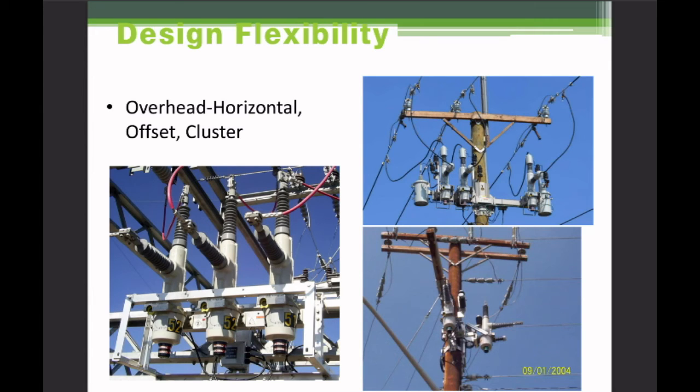If we take a look at this one, for example, you'll see there's 3 individual switches, and they go back to a central control box that'll feed down the pole. And so this is a triple single switch, so it could be operated single phase or 3-phase, but again, whether it's 3 single phase switches or 1 3-phase switch, that's controlled by a computer.